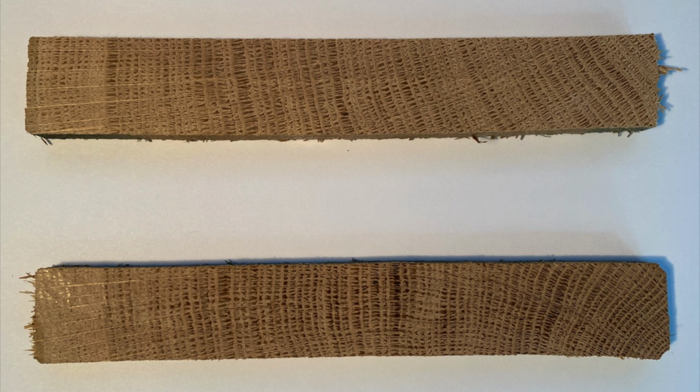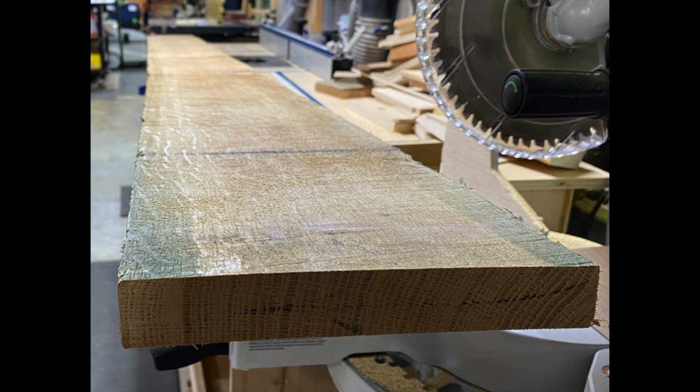However, that's not always a guarantee. You'll also notice on the right edge that the corner is getting close to the pith of the tree, or the center. Since wood warps typically occur away from the pith or towards the bark, this board should have a bow to the outside, and sure enough, it does. So now I know that this board, except for the one edge nearest the pith, will work well, since straight grain is a requirement for my particular project.